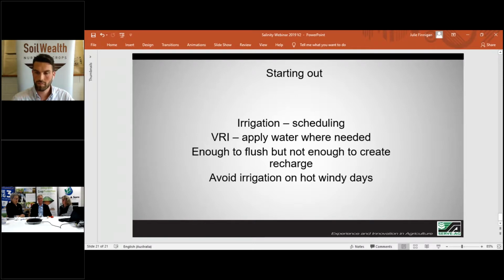That's right. And if you use capacitance probes, make sure they're calibrated properly, because different soil textures give you a different result, because they measure water content. So 20% in the sand is nothing, and 20% in the clay might be all right. So it's really important to actually get really good information on the monitoring gear and understand what it actually does, and not just get some kind of wiggly lines. And the capacitance probes, they're a little bit more expensive as well. So again, if you want to make sure you're putting it in the right place, you need all the background information.